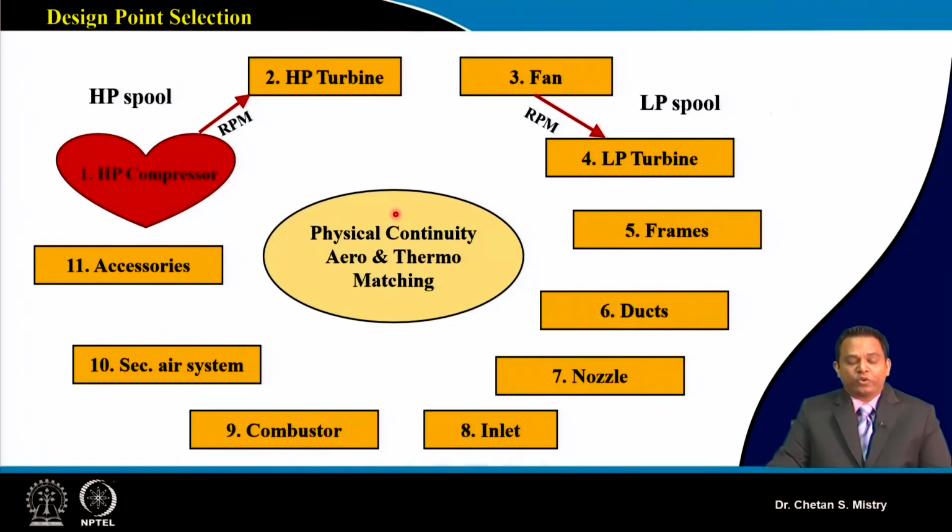So we have physical continuity, and aero and thermo matching come into the picture. There is a specialized branch in engines where people talk about aerodynamic matching and thermodynamic matching. That is very important. All the components we have designed need to be matched both aerodynamically and thermodynamically. If they are not matching, it is of no use.